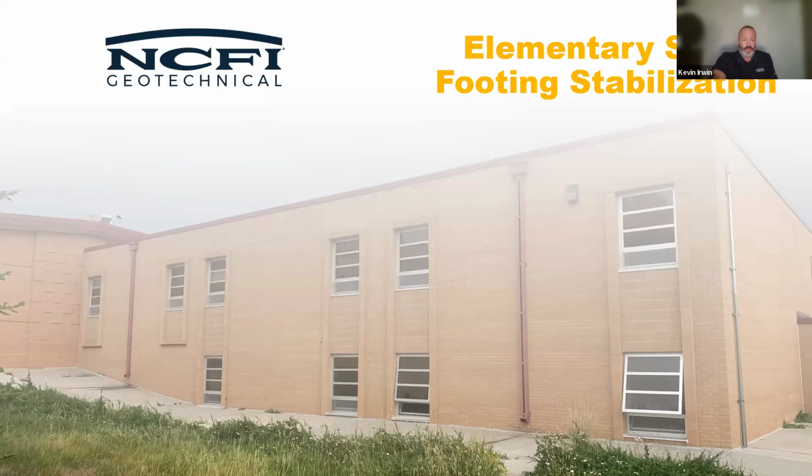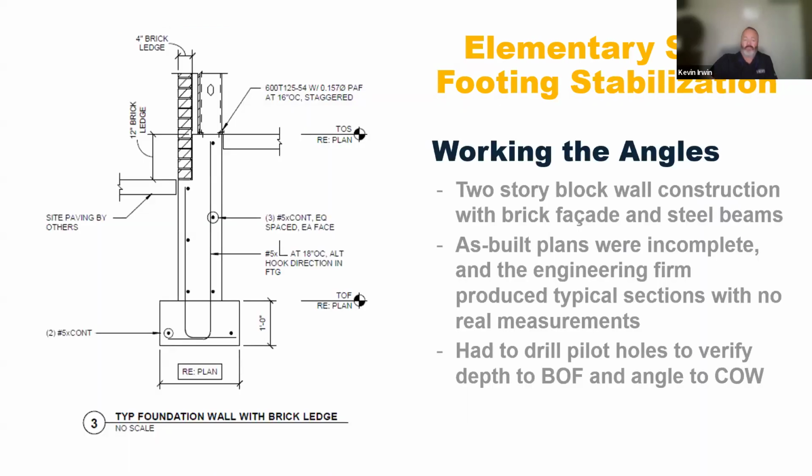And then footing stabilization. This is a 2-story addition on an elementary school building. The footing was roughly 3 to 4 feet below grade. It had a narrow spread footing that needed to be supported, and so this was a deep injection application. The goal was to get our chemical directly underneath the center line of that wall. So if I have a center line of the wall here, I wanted that chemical somewhere directly below that center line as much as I could.